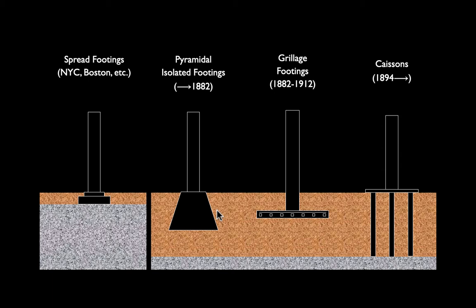And they really came up with the science of spread footings, first using stone pyramids. And then once the steel and iron industry began making rails in the city, using what were called grillage footings, basically grills of steel I-beams that could act literally as reverse slabs, handle the immense shear that some of these columns were beginning to put onto the foundations.